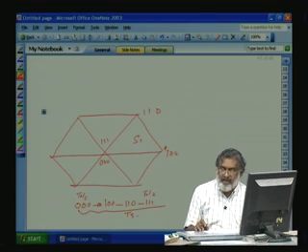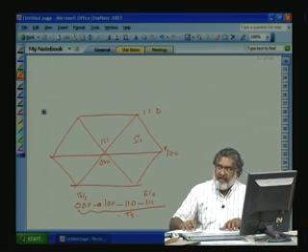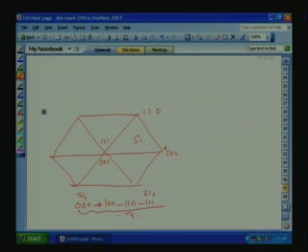In the next sampling period, we will start with 111. So, that will ensure minimum switching. Then we will go to 110, then 100, then 000. So, if you see here, this is the next sampling period. So, the inverter started with a 000 state and ended with 000 within 2 sampling intervals. That means, in 2 TS, the inverter has come to its original state. So, the inverter switching period is equal to 2 times the TS.